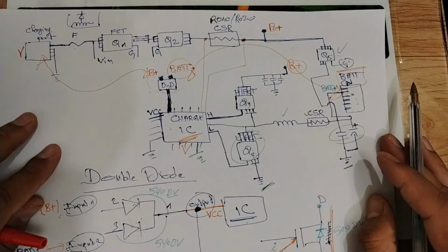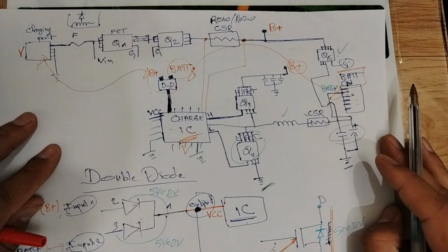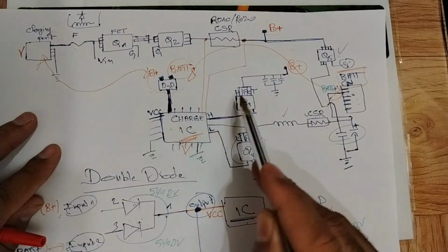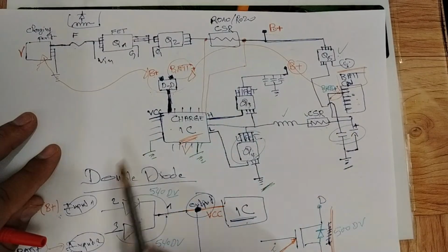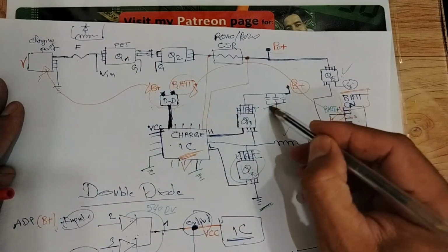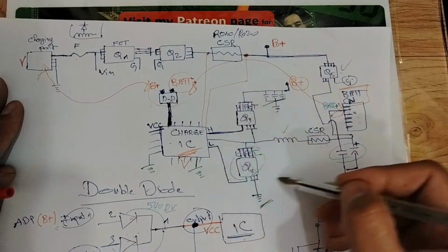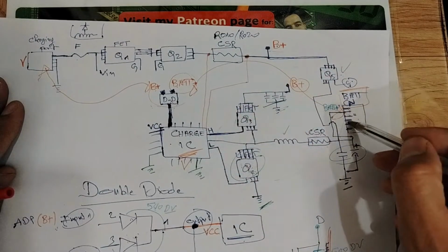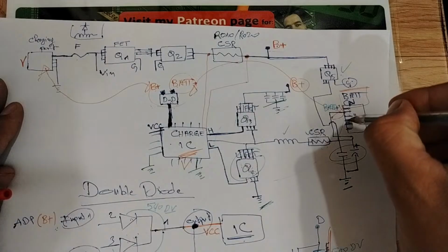So, Mr. Alexander, check the charge IC, MOSFET, ceramic capacitors. Charge IC, MOSFET, ceramic capacitor. That's it. And of course, the output also could be failed. Those also, if shorted, you will get something hot next to the battery connector.